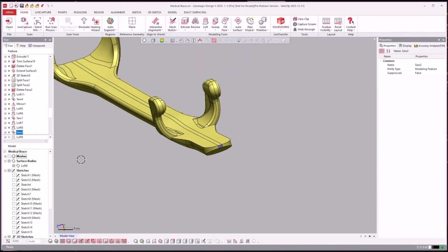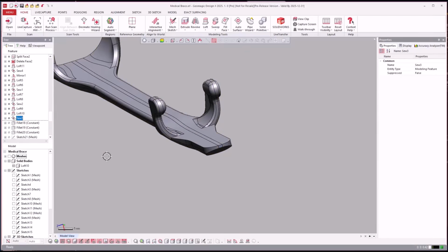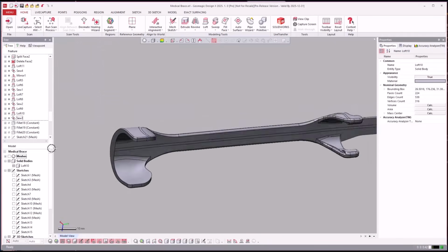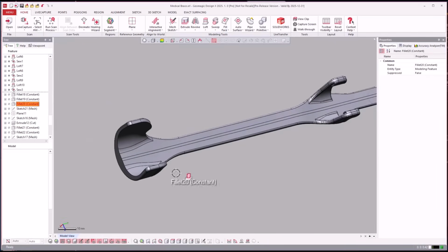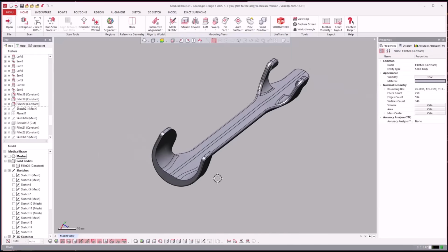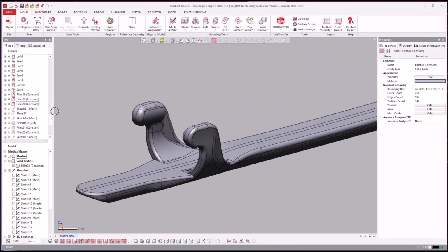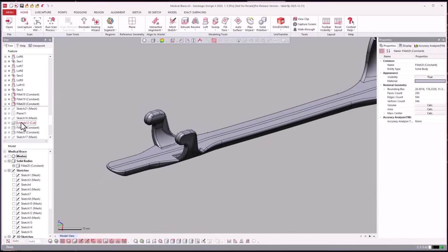You see we still have a little piece down there. So we're going to loft, sew. Boom. And as soon as we sew it and it's a bounded shape, it becomes a solid there. Then we come in and we add some fillets, filet mignons. And then let's see where we go here. I think there's some cleanup work that still needs to be done.